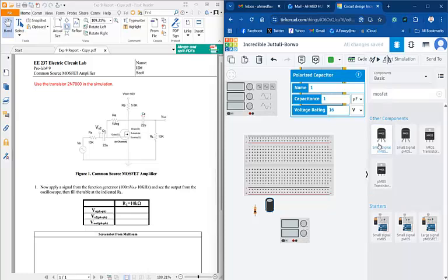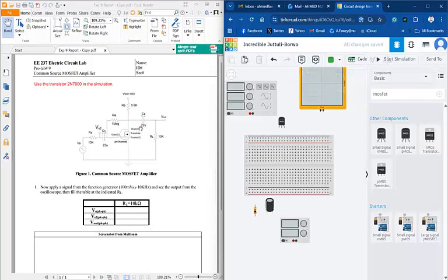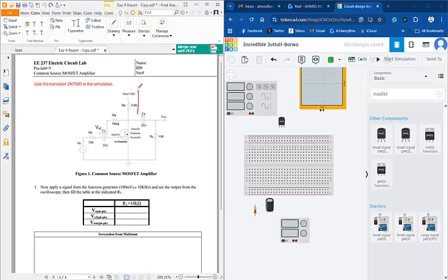And here look for the MOSFET N1. Like what I have said, there are three legs: drain, gate, and source. So let's now connect the circuit. We are going to start with the transistor. It is N channel. So first let's connect this circuit. After that, we are going to implement the rest.